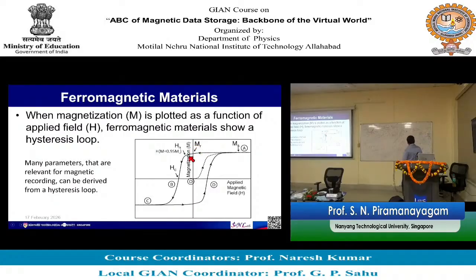Now I go in this direction. I am applying a field in the opposite direction. Initially I was applying field in a certain direction, now I am applying field in the opposite direction. That will make some of these magnetic moments switch. At some point you will have roughly half in the same direction and half in the other direction. At this point the magnetization becomes 0.